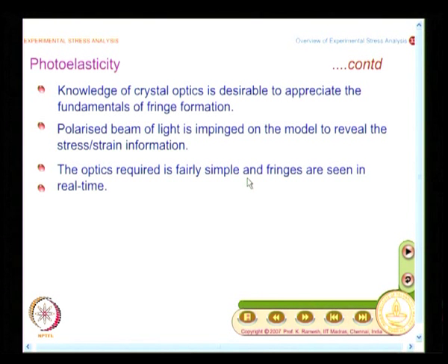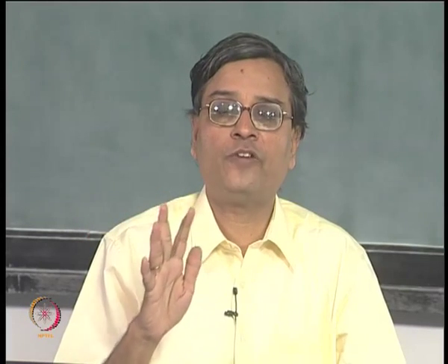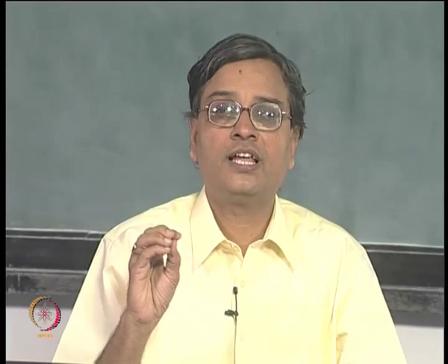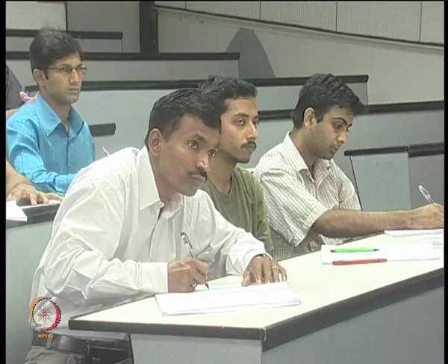This is very important. If you go to any one of the experimental techniques, for example, if you go to holography, you will have a double exposure. Only after processing you will know how the fringes are. So, you do not have any guidance while applying the load on whether the symmetry is maintained, all that you will not be able to know. But with developments in computer based processing, you could make even those techniques real time. So, when you look at any of the whole field optical techniques, one of the aspects you look forward to is it providing fringe information in real time, and photoelasticity does that.